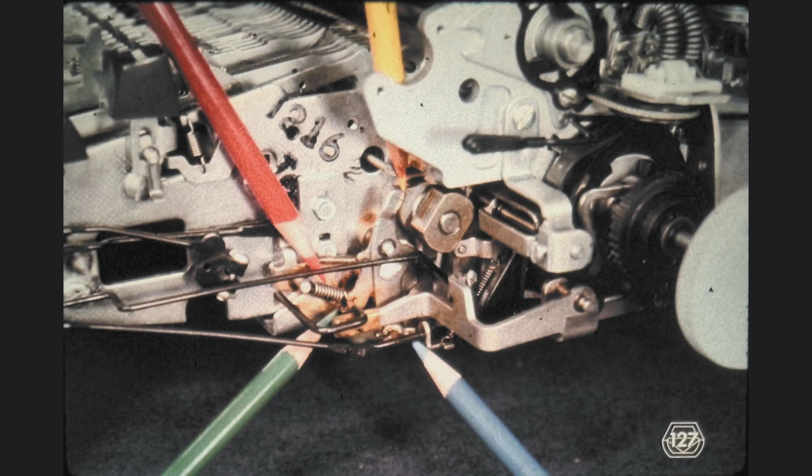The front-to-rear clearance between the low-velocity selector latch and the cam follower, at the point indicated by the green pencil, is also adjustable. Notice that this low-velocity mechanism cam follower is made up of 2 parts, one which rests on the cam, at the yellow pencil, and the other, to which the low-velocity mechanism drive spring, at the red pencil, is connected. The 2 parts are held together by the rather large adjustment screw directly under the pivot point of the cam follower.